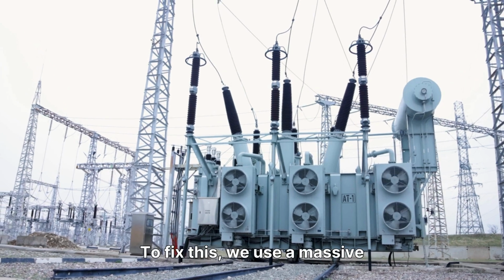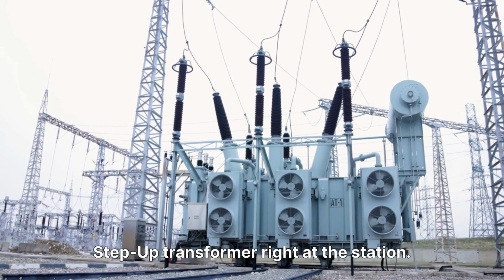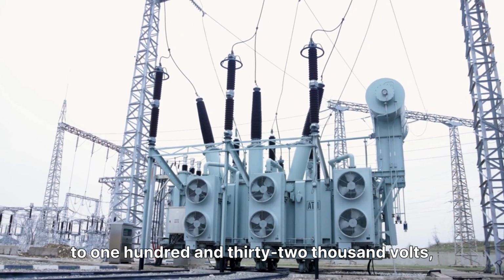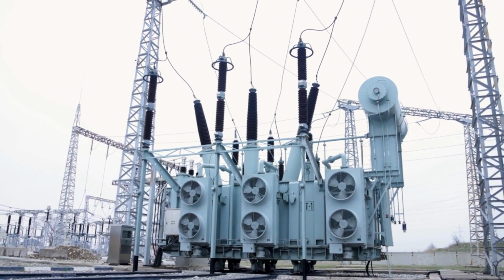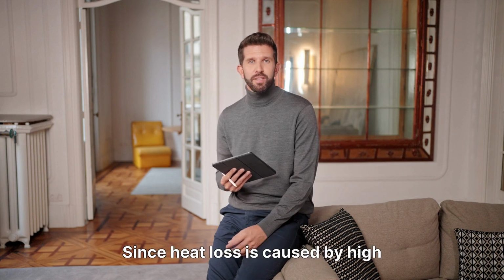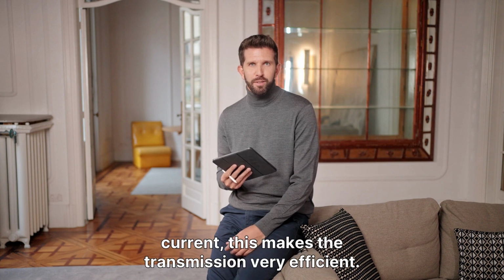To fix this, we use a massive step-up transformer right at the station. We step that 11,000 volts up to 132,000 volts, or even higher. By increasing the voltage, we drastically lower the current. Since heat loss is caused by high current, this makes the transmission very efficient.